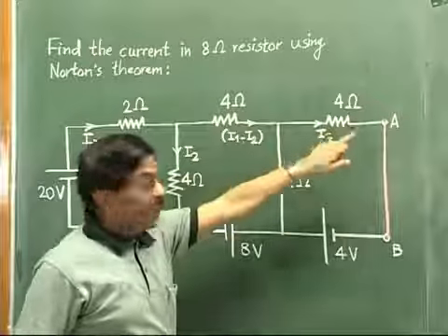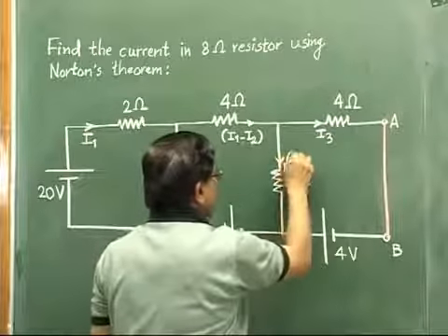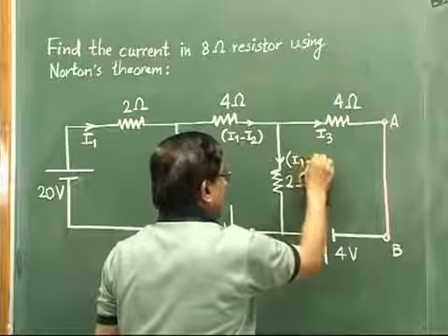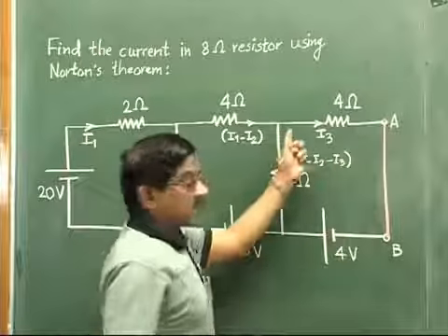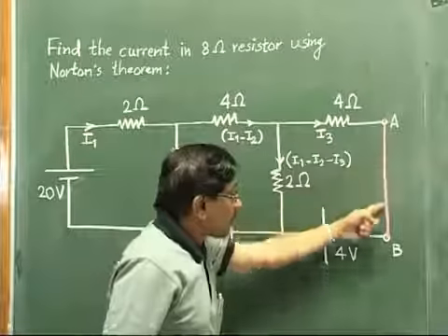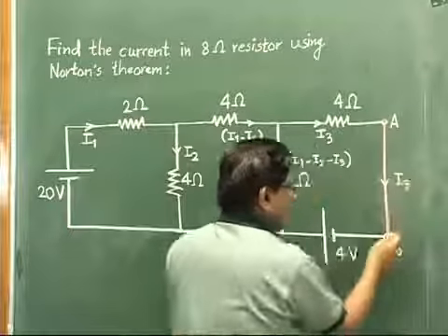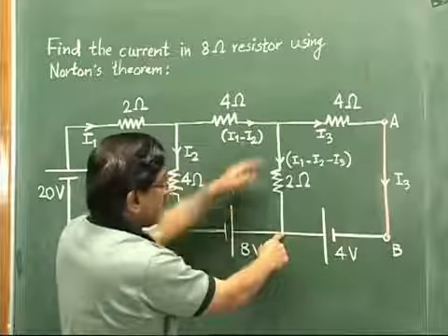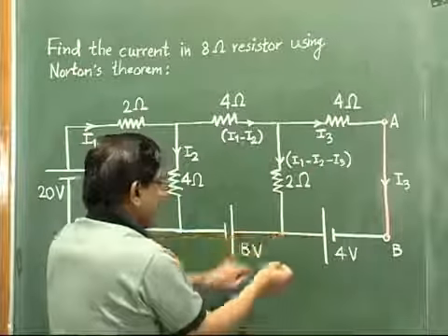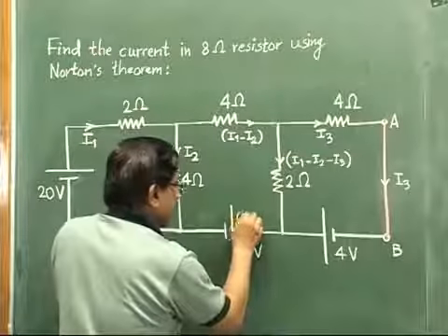Now see, I3 goes here. So what current will come down? The current coming down would be I1 minus I2 minus I3. Now see here, this I3 will flow through this shorted link. So here I will say that it is I3. It will come down, then through this battery, the I3 will reach here. These 2 currents meet. And then what current will go ahead? The current here would be I1 minus I2.